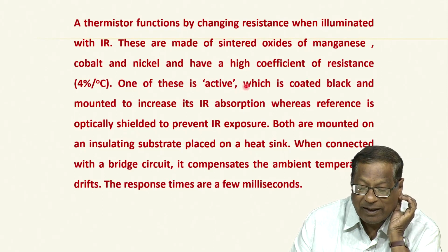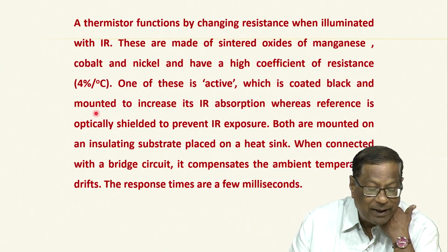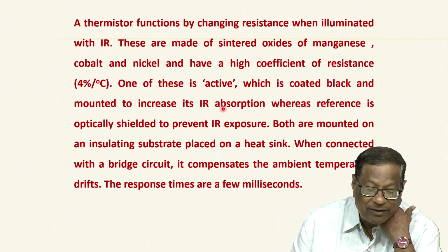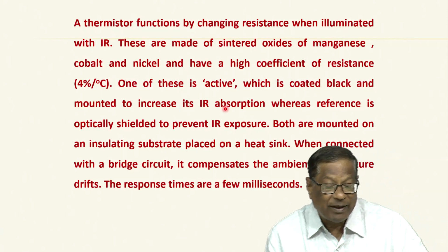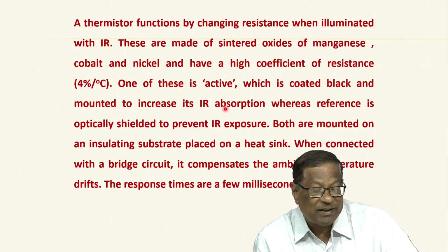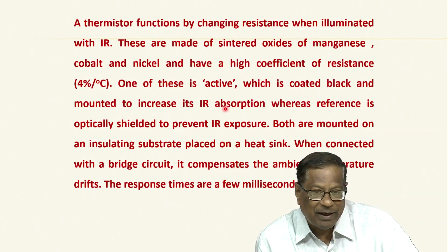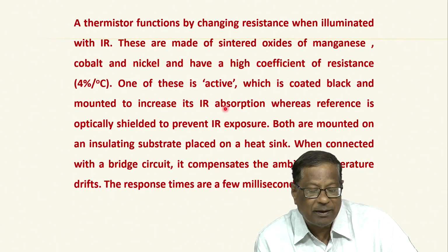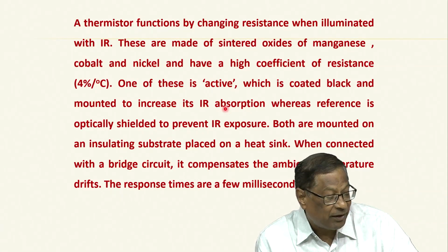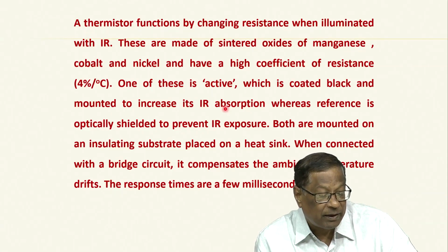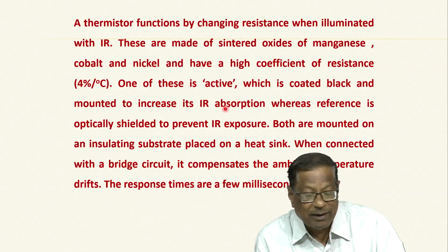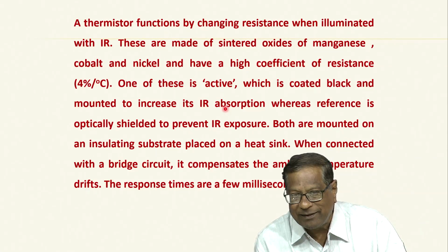One of these is active, which is coated black to increase its IR absorption, whereas the reference is optically shielded to prevent IR exposure. Both are mounted on an insulating substrate placed on a heat sink. So, when connected with a bridge circuit, it compensates the ambient temperature drift also. The response time here is about a few milliseconds.